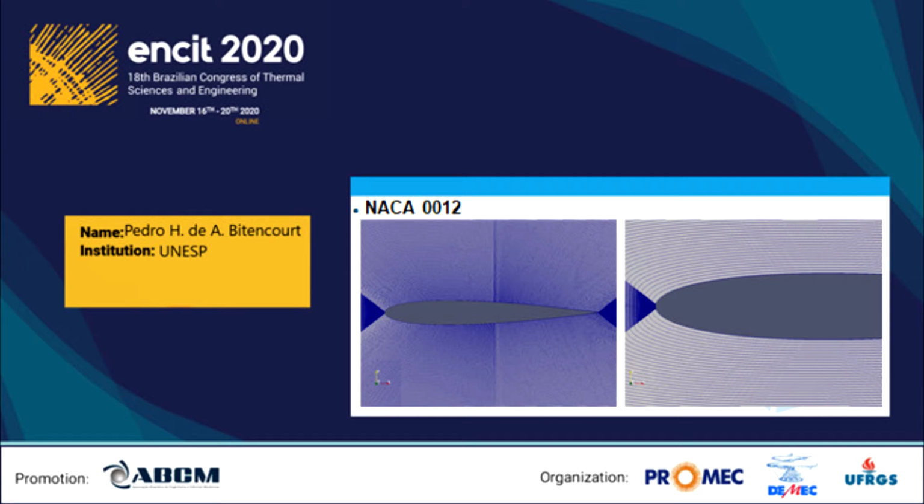elements. Since OpenFOAM operates with a three-dimensional mesh, even for two-dimensional cases. As you can see, the left image shows the mesh around the airfoil, while the right focuses on demonstrating the mesh around the leading edge. Two other meshes with different values of y+ were generated for the GCI analysis.